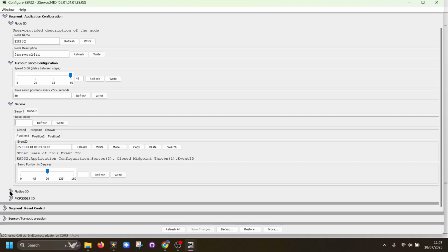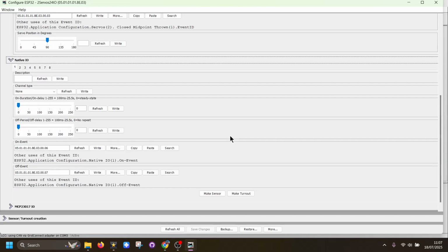So the next thing we've worked on is, with the ESP32, we found that we couldn't use all the pins as inputs and outputs. So we decided to stick with 8. I found out there were 8 pins we could use. Now, I might change the front screen where you've got the 1, 2, 3 and put the numbers of the actual pin up there, because that might be handier. That won't take long to work out. So that might be a part of a future release.